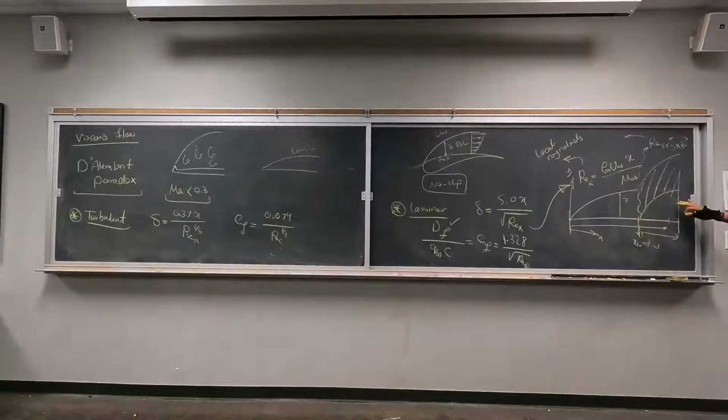So you're telling me that I have to use this friction coefficient plus the laminar. This part is the laminar contribution, right? Is that what you're saying? Yeah, plus that one spot at the end. Your friction coefficient equation is not a function of delta. So what do you see? This is 1.328 divided by the square root of Reynolds number. Delta would be a constant there.